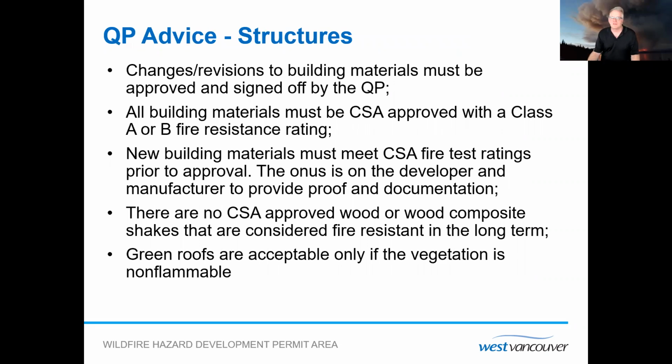QP advice on structures. So changes, revisions to building materials must be approved and signed off by the QP. I've had numerous examples where we've written an assessment, the materials were agreed to at the front, and developers have decided to change them with non-compliant materials, and we can't sign off on those as a QP. Creates a huge headache for the developer, huge headache for us. And usually there's not a substitution alternative. And in some cases, it's come down to we've had to enforce the home being sprinklered as the only option to protect the house.